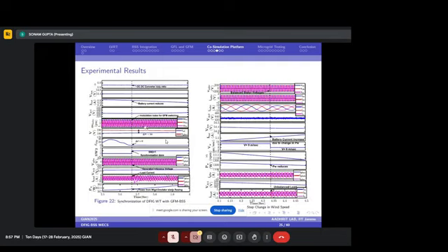So we have some experimental results for this co-simulation platform. The synchronization of the DFIG battery storage system with the grid forming battery storage, we can see here at switch S2, in between 5.6 to 5.76 seconds, because around 5 seconds will be taken to complete the sequence. Once the sequence is complete, the synchronization will become active. It will be enabled from 0 to 1, and after that we can see that it will start generating the reference as well.